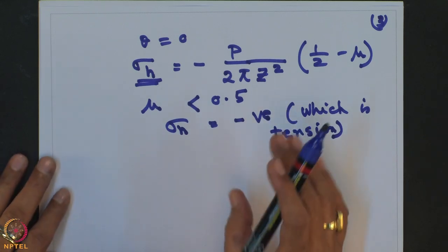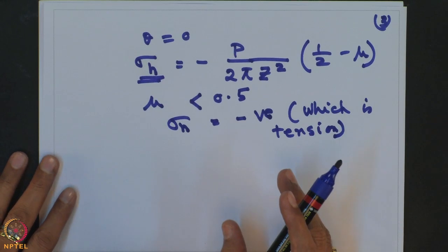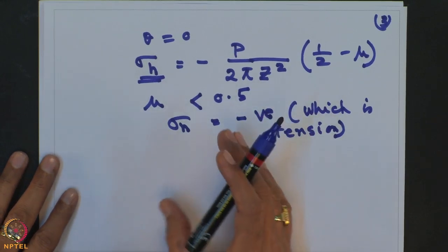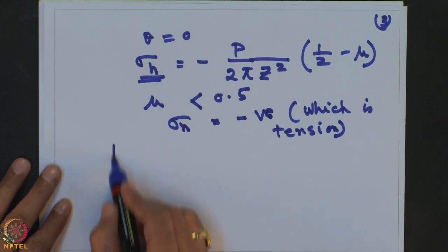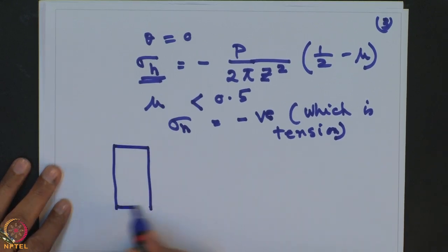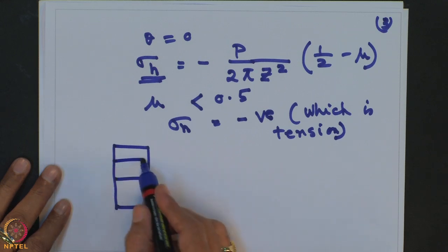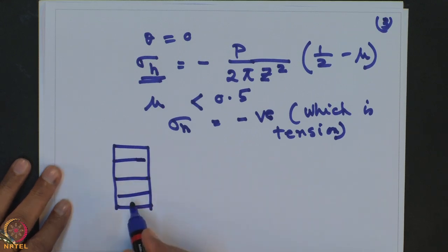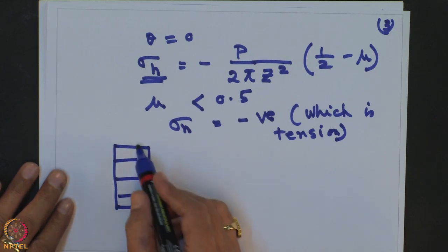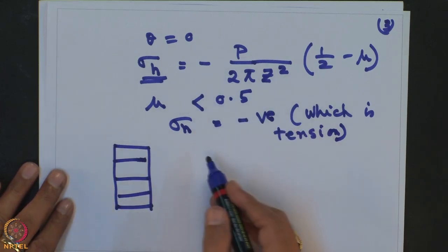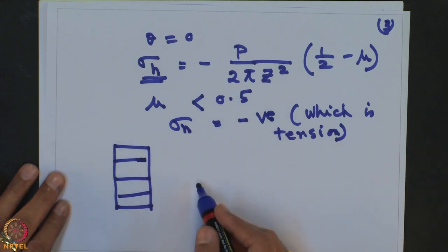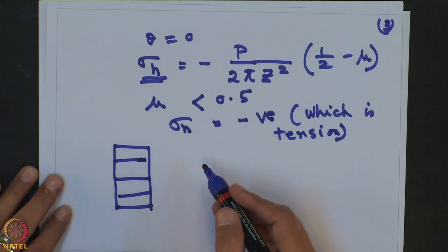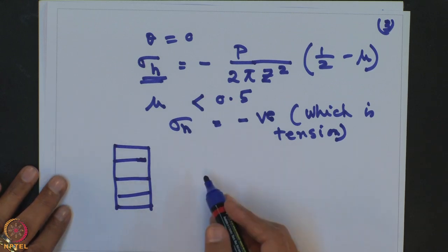So, as you place the geotextile material closer and closer, okay, for example, this is the triaxial soil sample, if we place the geotextile material closer and closer, so what will be the load? The load will be higher. Then the tensile stress value is higher. That means the required tensile strength of the geotextile material is higher.